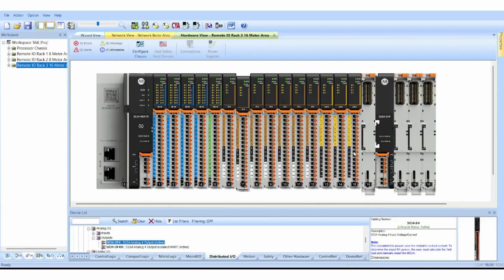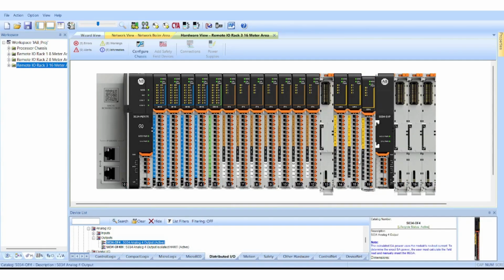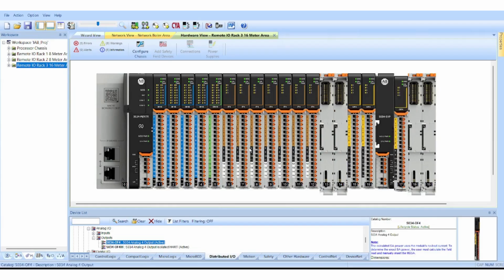First, it gives us a high-speed communication backbone between the different refinery areas. Second, fiber provides excellent immunity to electromagnetic interference. This is particularly valuable in an industrial environment containing large motors, variable frequency drives, MCC panels, and high-power electrical equipment. Fiber also provides electrical isolation between the interconnected areas. So this is not simply a decision based on distance, it is also about creating a robust industrial communication infrastructure.